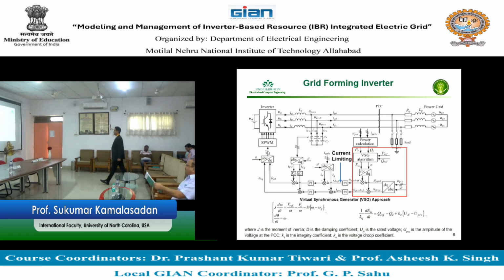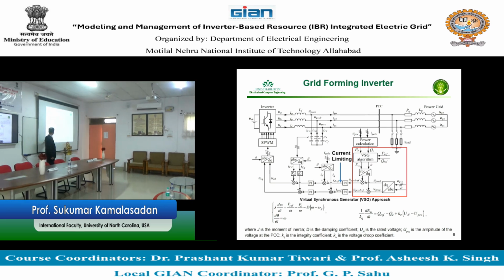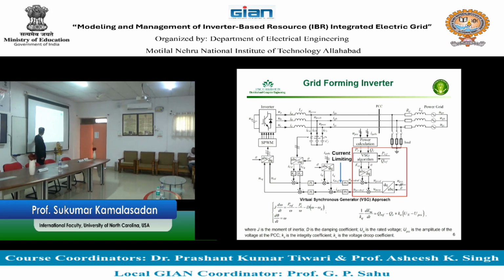So if you have a synchronous generator model, right here, d theta divided by dt is equal to omega, d omega by dt is the reference Pm minus Pe, and you can also include damping, delta omega divided by omega. This is a synchronous generator swing equation model. That swing equation model can be included in this, like a map, just a map. So if you do that, is this power something you know? Well, your power you know. That's coming from the output of the inverter.